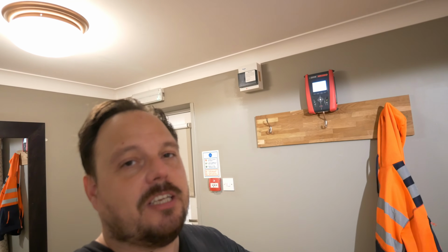So I hope you found that interesting, having a look through the EICR. You can see the test results came out as we would expect based on what is installed. The observations in terms of any physical damage to equipment weren't really anything at play. There are some questions around coding on this plastic consumer unit and on the potential issues around the supply arrangement to this particular area and no RCD protection.